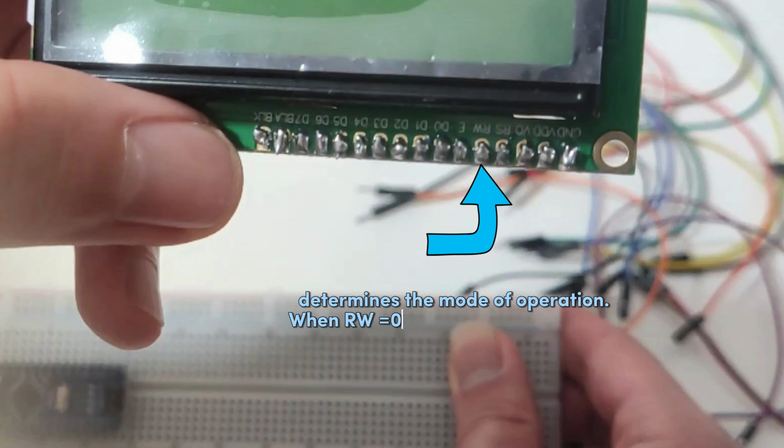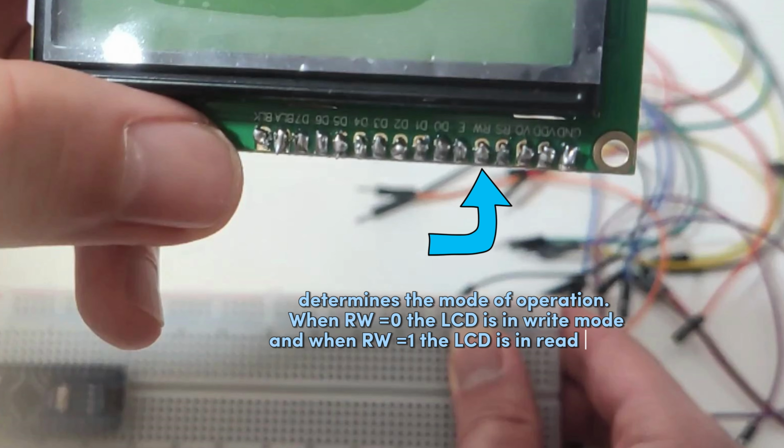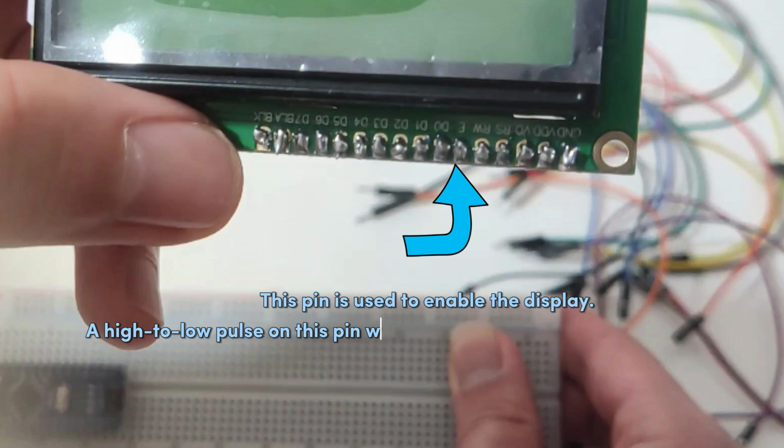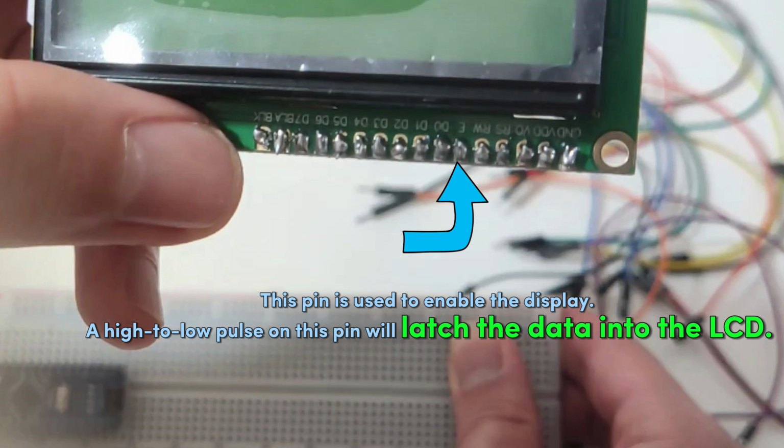Continuing, we have the RW, or Read-Write pin. This pin determines the mode of operation. When RW is equal to 0, the LCD is in write mode, and when RW is equal to 1, the LCD is in read mode. As our next pin, we have the E pin, or basically the enable pin. This pin is used to enable the display. A high to low pulse on this pin will latch the data into the LCD.